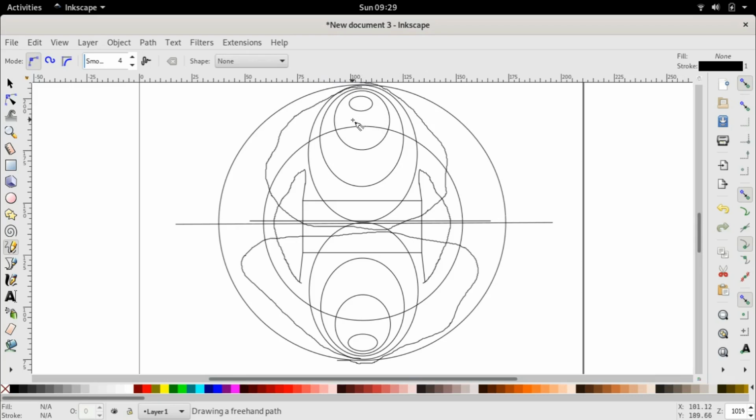The reason is that now the flux produced by these stator currents has a low air gap path for it to flow through. Now it's important to understand, as I said before, that the reluctance of iron is much lesser than that of air, almost 1000 times lesser.